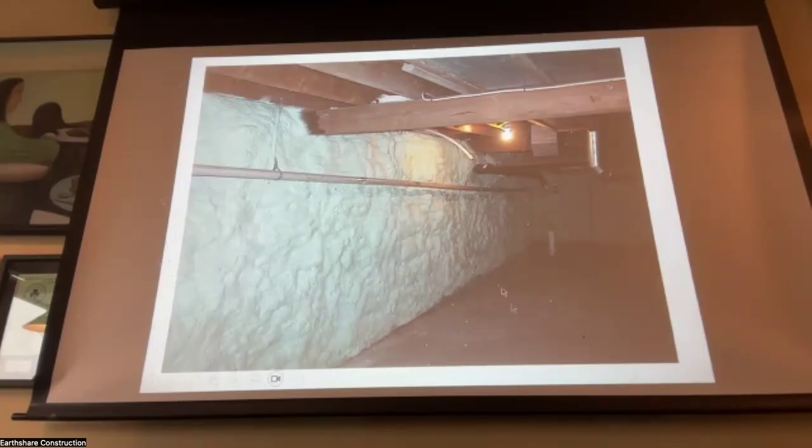So are you advocating for 15 mil poly coming across the slab and up the walls, reinforced, with UV stabilized? We always use the product called True Tough. I don't know if it still exists. Stego Wrap. Yes, something that won't degrade due to ultraviolet. And I'm here to tell you there is ultraviolet in crawl spaces even. Certainly there is ultraviolet in basements.